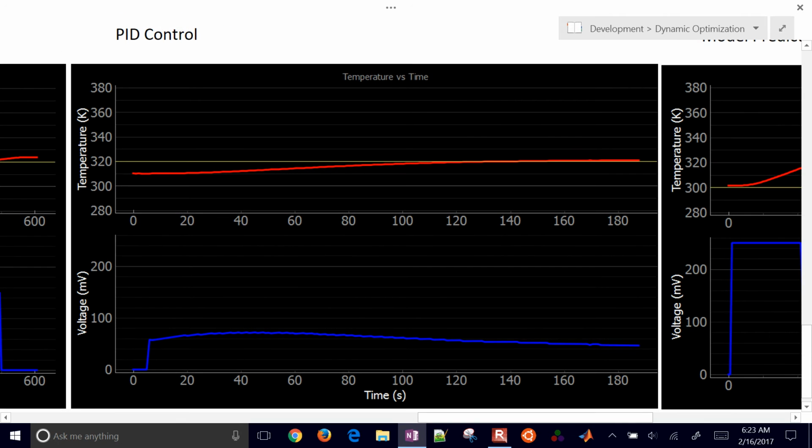So if the heater can turn to not just on-off, but to specific values that are in between on-off, then we can use a PID controller. And so in this case, you see there's less oscillation once the PID controller reaches the set point in this region. But this could probably be tuned a little bit better to come up to the set point faster. Okay, so that's a remaining challenge for this one.